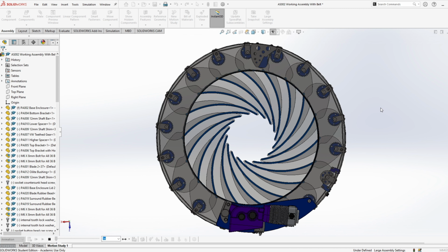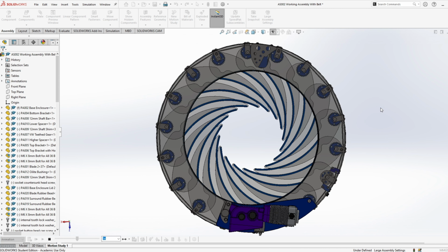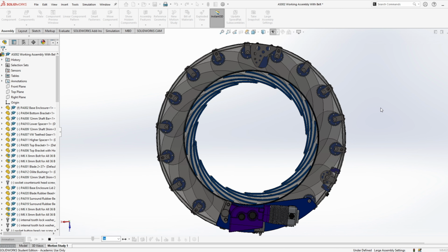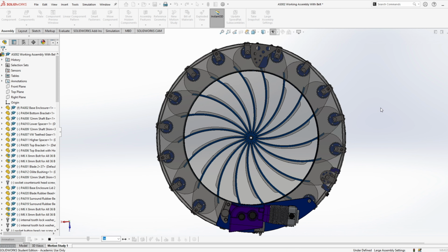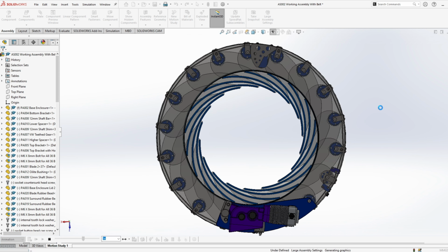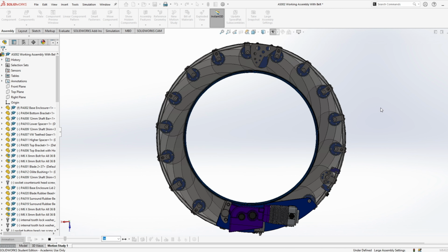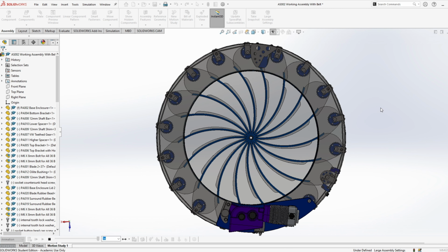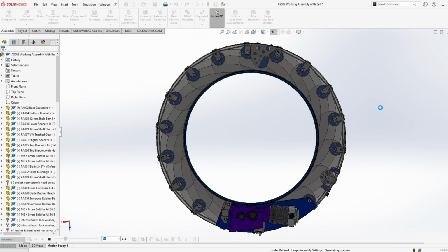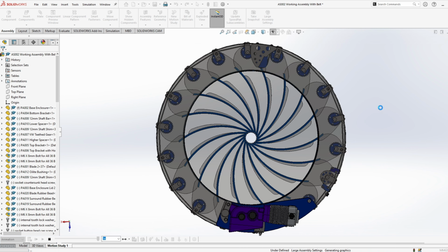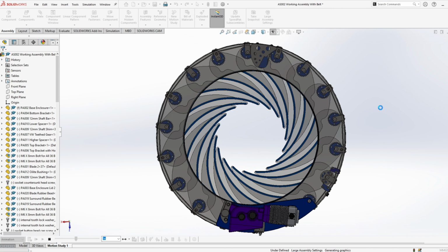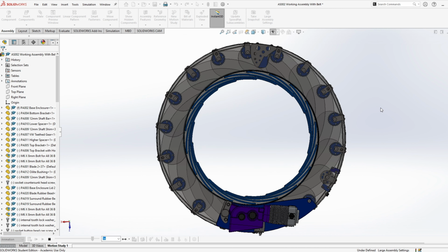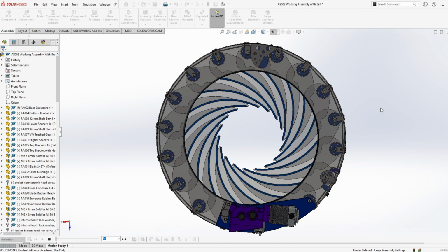Okay, to make these changes all work, I needed to obtain another HTD timing belt, a little longer this time, as not only did I decide to use a wheelchair motor and gearbox to drive the belt, but I also decided to tension the belt with the same unit rather than using an additional adjustment tensioner. It's very important for this belt to be extremely tight to reduce belt slippage, as the belt only rests upon 3 teeth of each gear, owing to the close proximity of neighbouring gears along with the large belt circumference.